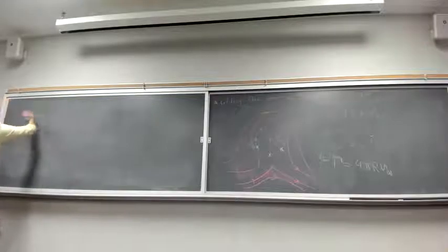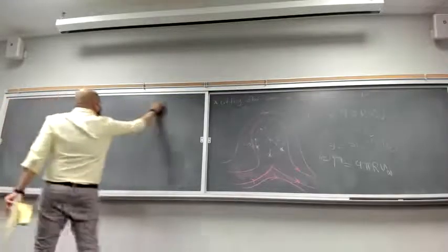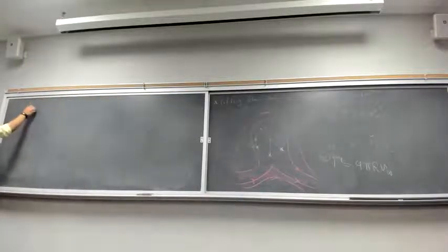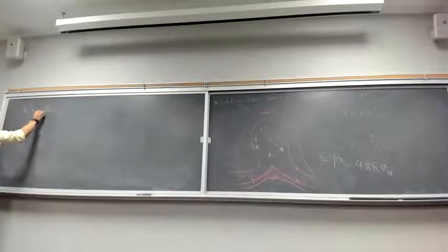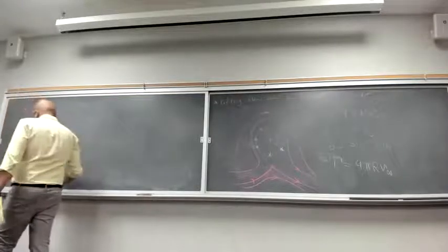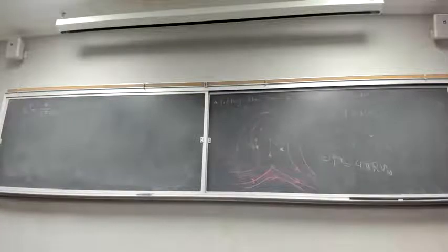That's right. So for vortex flow, you have gamma, which is circulation, the strength of the vortex. We have seen circulation before. We also have lambda for the strength of a source or sink, and kappa for the doublet flow. For kappa, you can always use the formula I gave you: R squared is kappa divided by 2 pi V infinity. So you don't need to use kappa, you can just replace it with that. And this is what we did here, because we had a doublet flow.